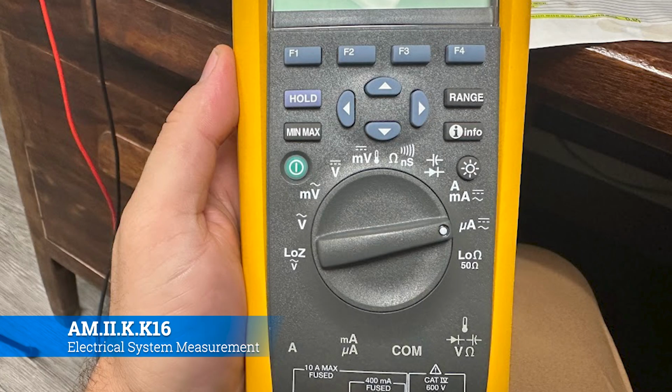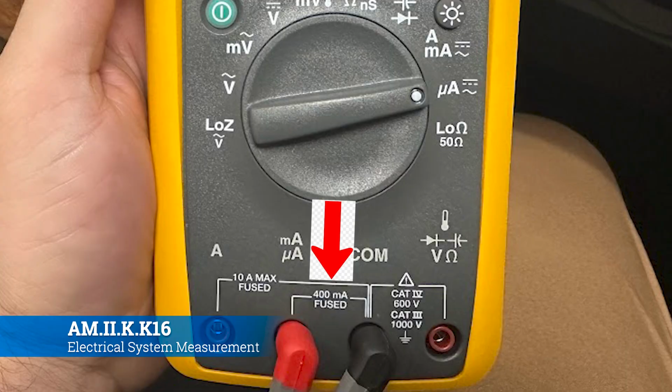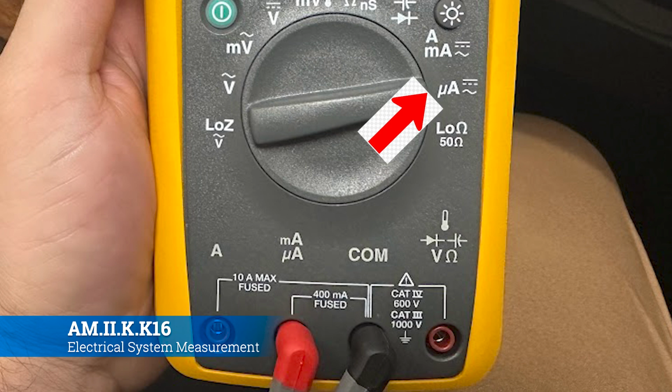Whenever we do amperage, we're going to switch our lead over so that it's fused. That way if we tie into a really high amperage, it doesn't blow the meter up. If anything, it'll just blow the internal fuse. But yeah, so we have millivolts AC, microvolts AC on that.